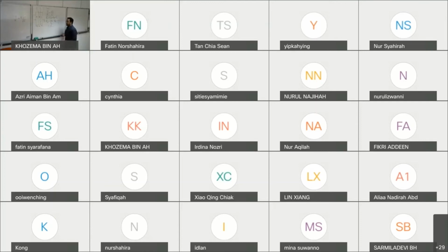And you know that the K value will have a unit of watt per meter Kelvin. So from here you can know that the unit of R is meter square Kelvin over watt. This is easy. If you don't remember the units, you can just find the unit based on the equation given.